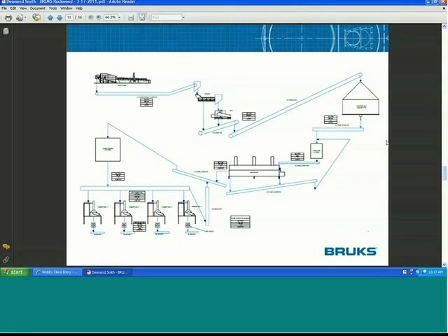A screw in the bottom of that would reclaim the material and take it down to that rectangular box, which is a storage hopper. That would then take it to the dryer, which is that thing with the three exhaust stacks on it. The dry fiber would come out of that and go over to the far left side. That's a storage hopper, and then a distribution screw would distribute it to, in this case, four independent grinders. These grinders would have an overfeed system so that the overflow would go circulating back around. These grinders would grind the material, drop it into a pneumatic line, and that pneumatic line would take it into the boiler.